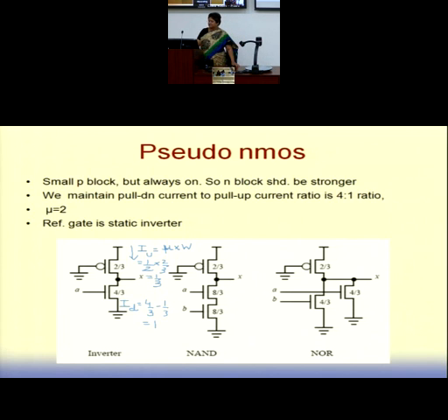Okay. Now, what is he doing? He is making it as 4/3. My standard CMOS inverter is still 2:1. Remember that. But here we are designing in the ratio of 1:4. So I want the drive capability as 1 for the pull up and for the pull down to be 4 times. Drive capability of pull down block to be the 4 times. So he has taken it as 2/3 and 4/3, assuming that mobility for PMOS is half of mobility of NMOS.